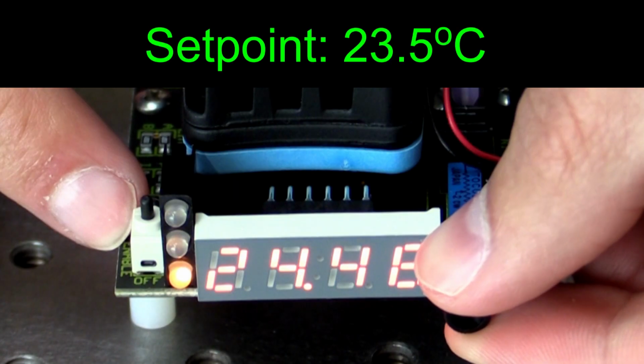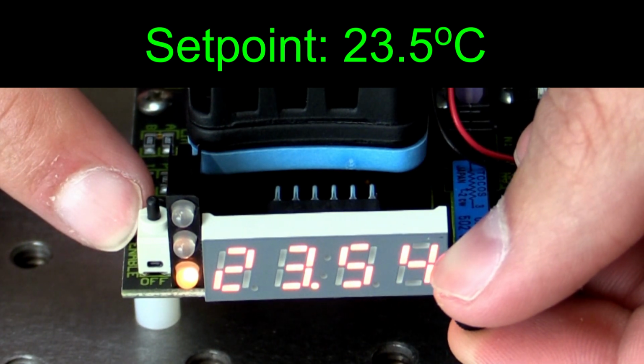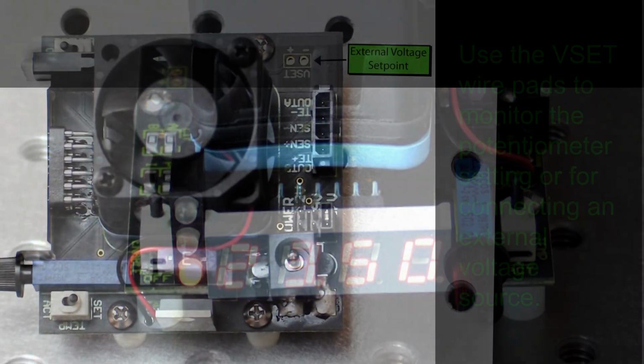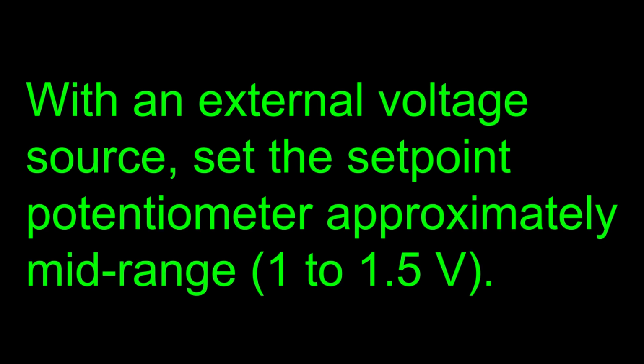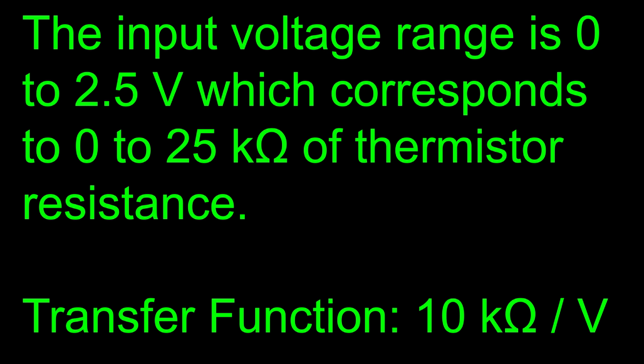The set point temperature can be adjusted from 10 to 65 degrees C either by using the onboard 12-turn potentiometer or an external voltage source. The VSET wire pads can be used as test points to monitor the potentiometer setting or for connecting an external voltage source, such as a function generator. If an external voltage source is used, set the set point potentiometer approximately mid-range, 1 to 1.5 volts. The input range is 0 to 2.5 volts, which corresponds to 0 to 25 kiloohms of thermistor resistance.